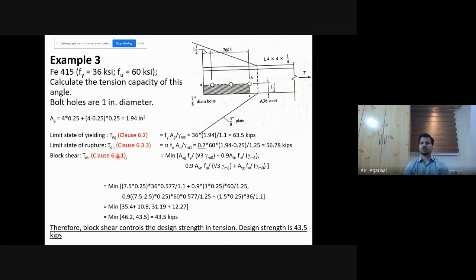Now comes the question of block shear. So block shear can happen only where the connection is. So for the block shear failure, the code very clearly. I'll talk about the more detailed calculation here. Instead of 56, in the next slide I'm doing a detailed calculation also, so that we will discuss in a minute. That number changes slightly, but that does not govern.